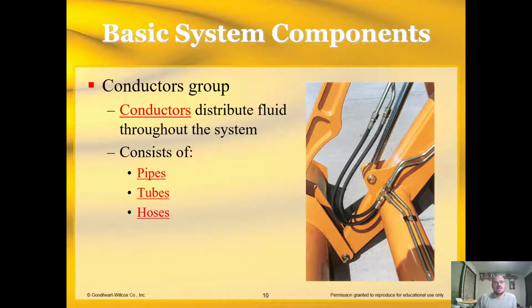Our conductors group. I always like to compare hydraulics and pneumatics to electricity, since it's all energy flow, right? In this case, conducting energy is done through pipes, tubes, and hoses with hydraulic or pneumatic power. So conductors distribute the fluid throughout the system. Anytime you have a hose or a pipe, those are going to be your conductors.